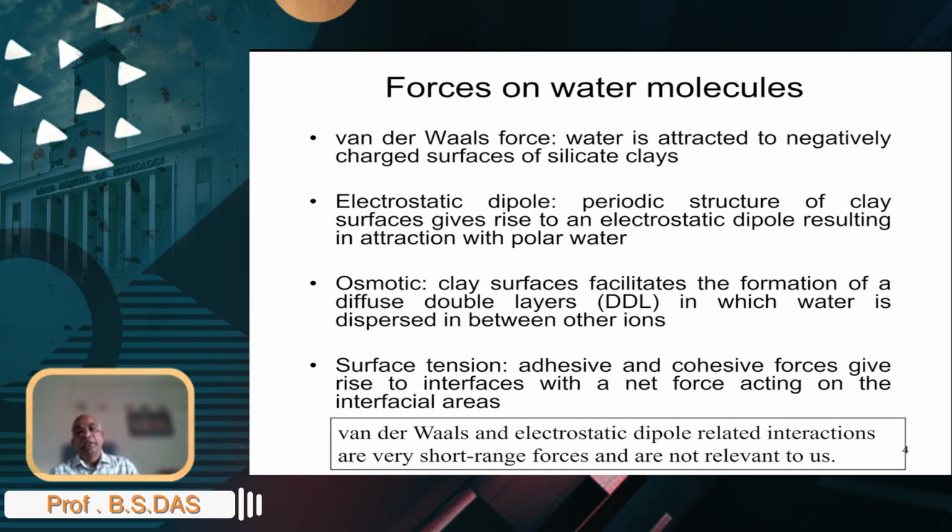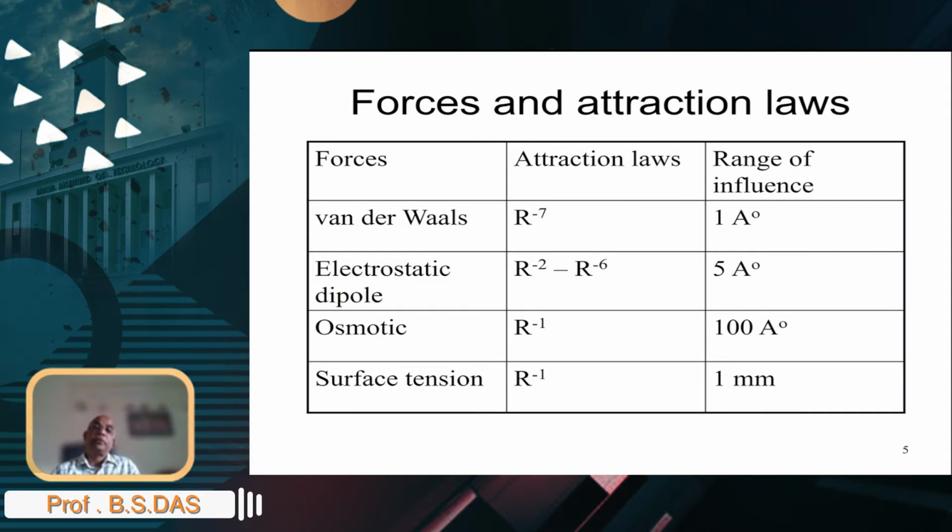So, as I mentioned, the attractive forces because of the van der Waals force or electrostatic dipole effects are stronger. Their range of influence between water and the solid particles is very small, in the order of angstroms, whereas when you go to osmotic and surface tension forces,